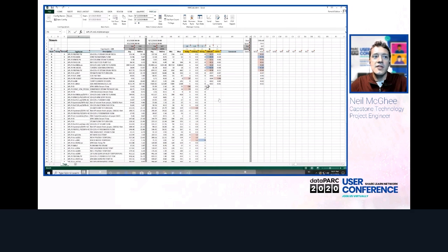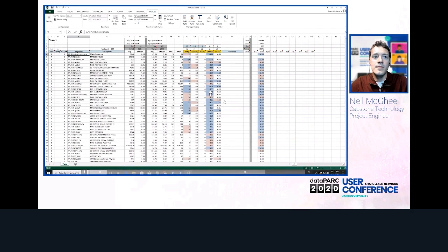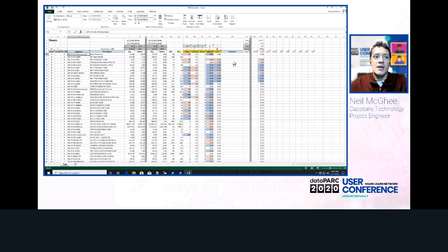If we instead look at Hotelling T-squared, it describes how much a tag's change contributed to a predictable change in the process. Hotelling T-squared is less helpful for finding individual tags that are having issues, but is more helpful for diagnosing the cause of larger shifts in the process.